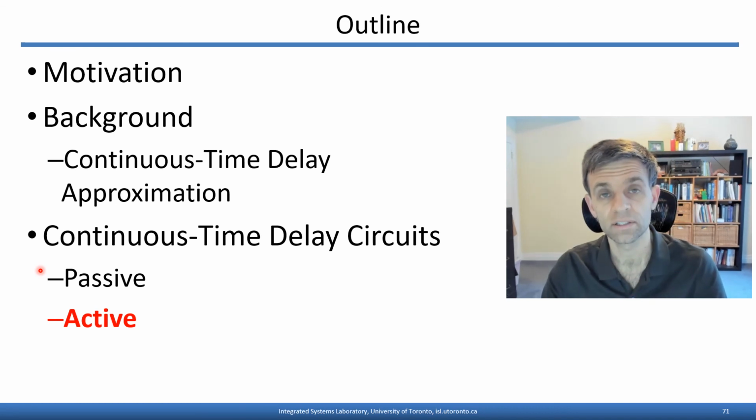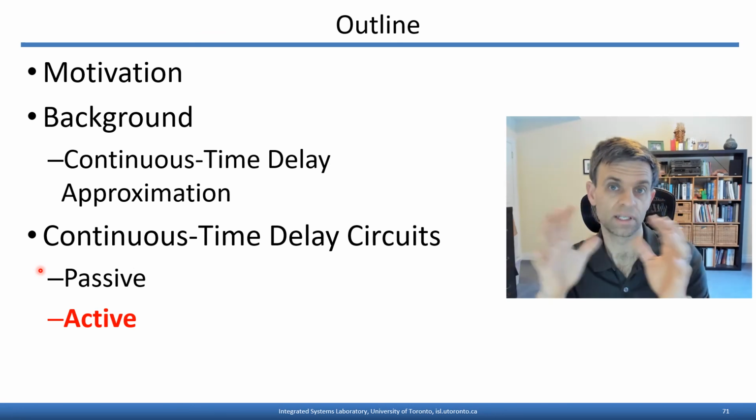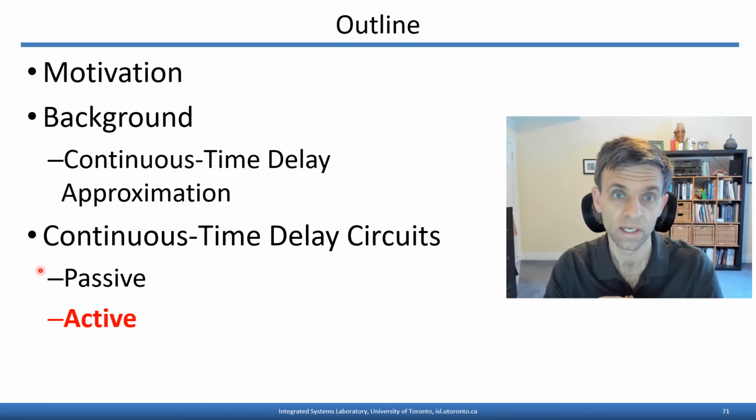Now, technology trends, fortunately, are affording us better and better metallization in the high layers of the interconnect. These have lower and lower series resistance, lower losses associated with them. At the same time, as applications proceed to higher frequencies, we're more and more interested in relatively short time delays, which allow passive delay lines to become more compact. So these trends tend to favor passive delay lines.